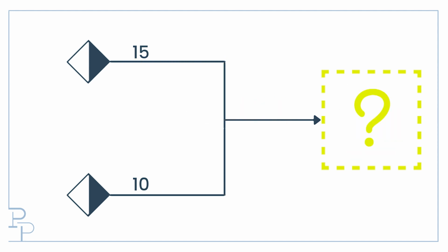To be able to work out all these details, you really do need to know not only the geometry of all this piping, the pressure drop characteristic of all these lines, but you also need to know the characteristic curves of both devices supplying the 10 bar and the 15 bar.